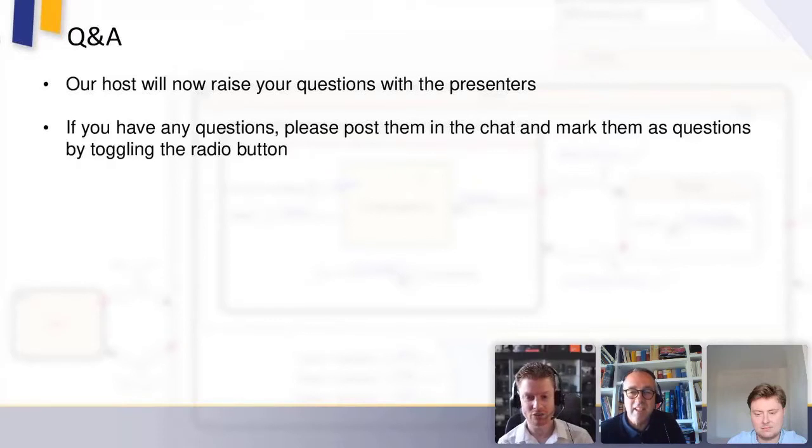Sure. Yes, I can just add to that, the RVS tools can run in what we call managed or unmanaged mode. In unmanaged mode, we assume that some other system is driving the inputs and outputs to the system, and we'll simply report either the execution time or the code coverage as achieved by that software. We can also run managed tests with RapiTest, which is where RVS is now responsible for providing the inputs and checking the outputs, and RapiTest is able to stub out functions so that you can simulate sensors and other things. Brilliant. I hope that answers your question, Martin.